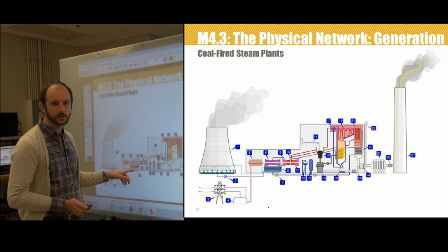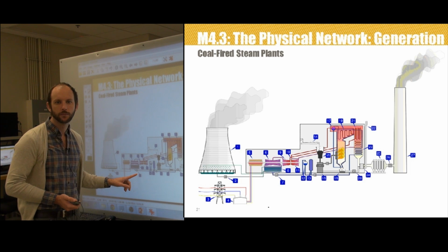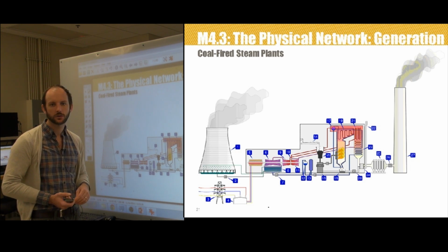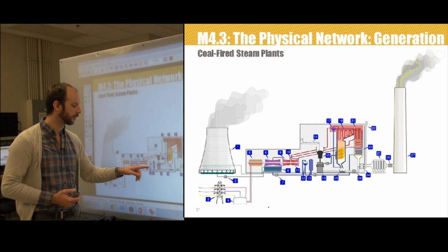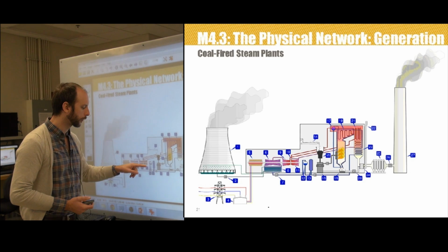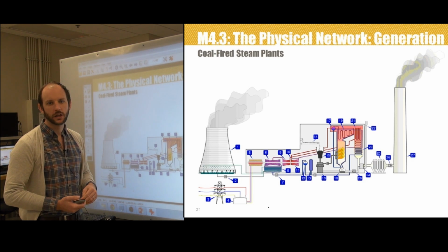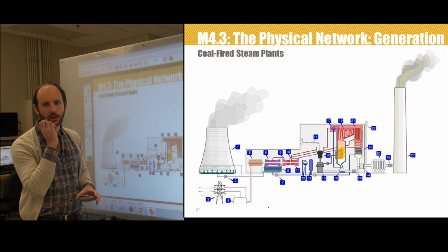The condensed water is then pumped out of the condenser by a feed pump. It then goes through what's called a deaerator to remove any oxygen or gases that have gotten into the water throughout this process, so it's going to remove those.